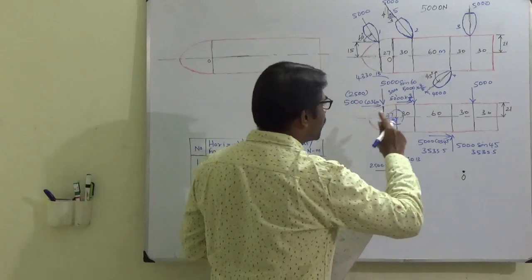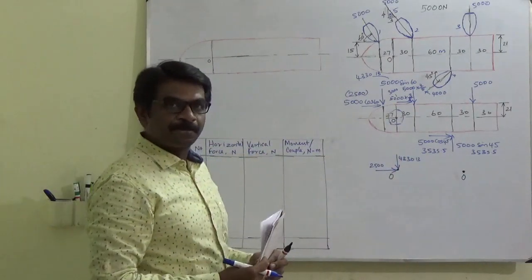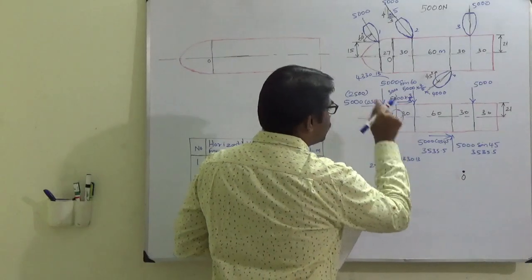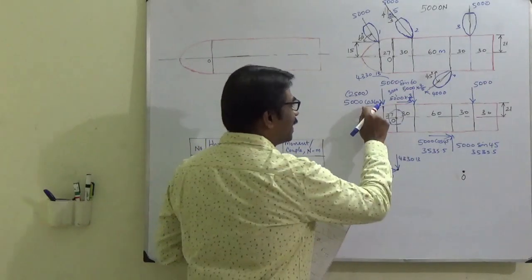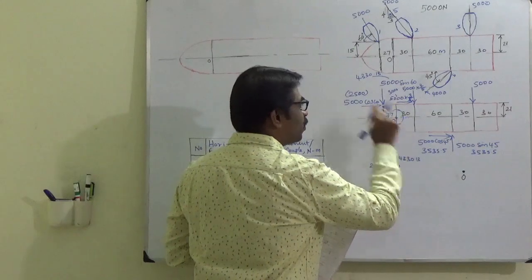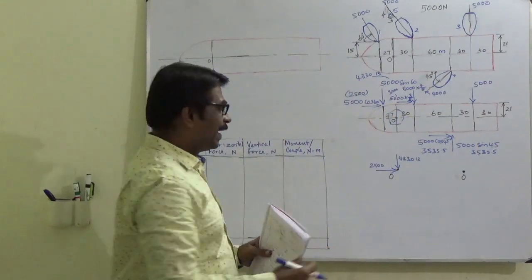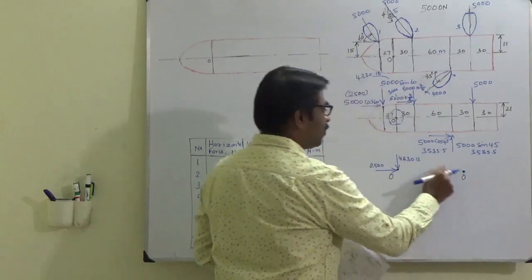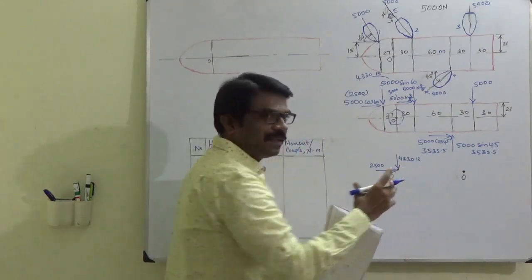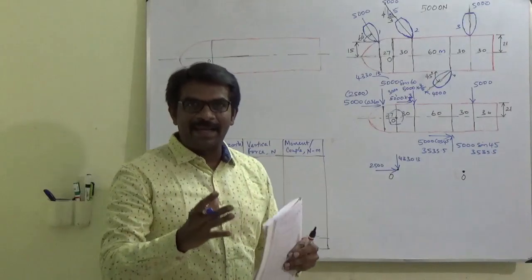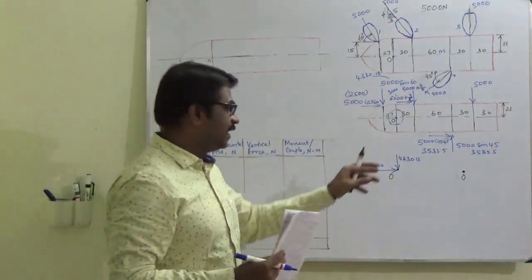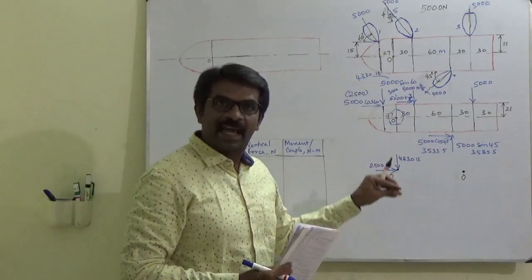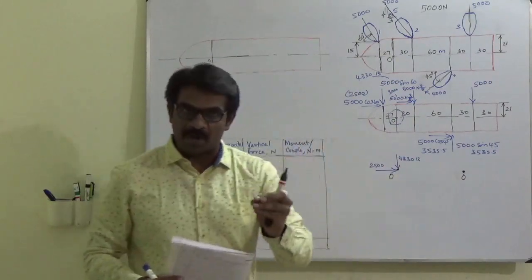We have to introduce a couple. So what is the couple that we are going to introduce here, which will be the moment of this force about O? Okay, I am placing all the couples and forces here, in order to make you clearly see each couple and its direction, each force and its direction. Actually, both are the same points.